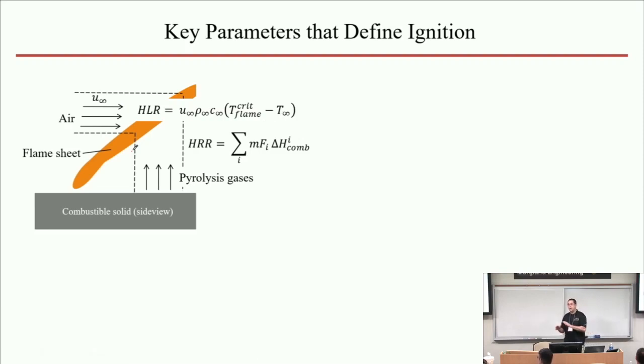And that's my attempt not to go into combustion kinetics and start talking about the rates of reaction and things like that. So I've replaced this complexity with a single parameter. It turns out that for many hydrocarbon fuels, for laminar flames, choosing it on the order of 1500 works quite well for a wide range of fuel chemistry. So you can make this approximation. This represents the heat losses from this flame. This represents the heat production of the flame. And of course, for the stable flame to exist, in other words, for ignition to occur, the heat release rate has to be either equal to or larger than the heat losses, right?